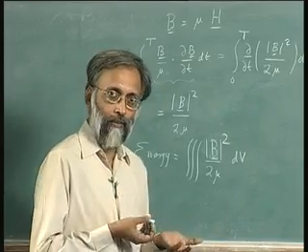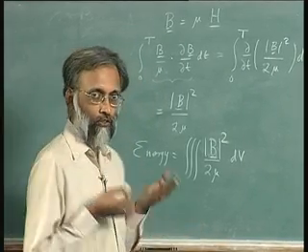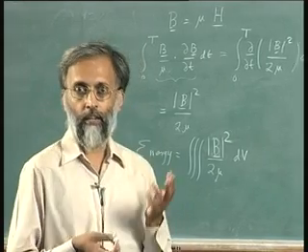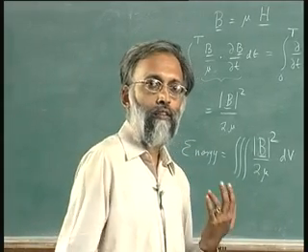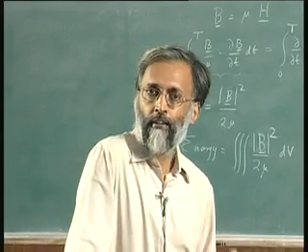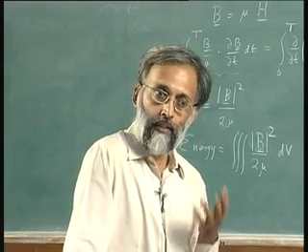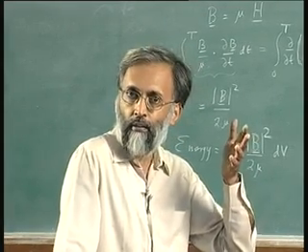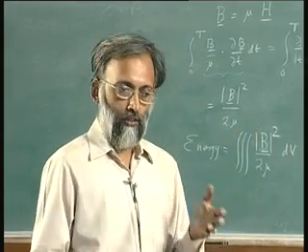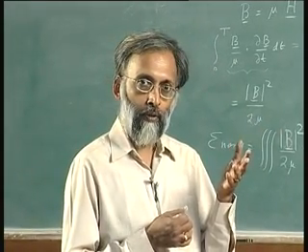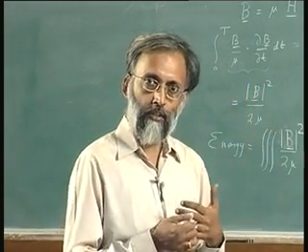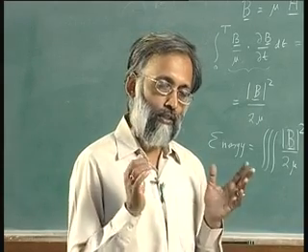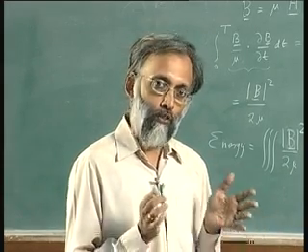As I said last time, this energy that we stored in the inductor came from somewhere. It came from the outside supply of electrical energy, but this energy rises to a peak when the current is maximum, but when the current comes back to 0, all that energy returns, which means this device is not a resistor.